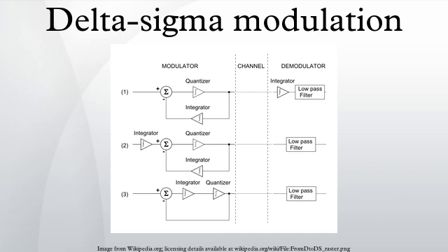the action of the feedback loop is to monitor the integral of v, and when that integral has incremented by the step, which is indicated by the integral waveform crossing a threshold, then subtract from the integral of v so that the combined waveform sawtooths between the threshold and the step. At each step a pulse is added to the pulse stream. Between impulses the slope of the integral is proportional to v.